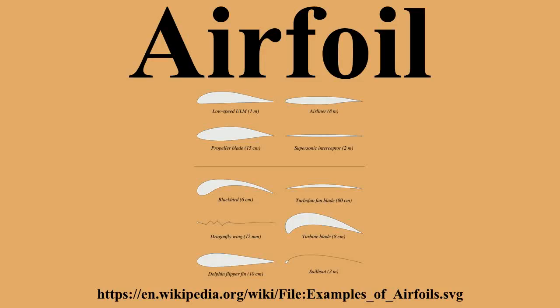A lift and drag curve obtained in wind tunnel testing is shown on the right. The curve represents an airfoil with a positive camber, so some lift is produced at zero angle of attack. With increased angle of attack, lift increases in a roughly linear relation, called the slope of the lift curve. At about 18 degrees this airfoil stalls, and lift falls off quickly beyond that.